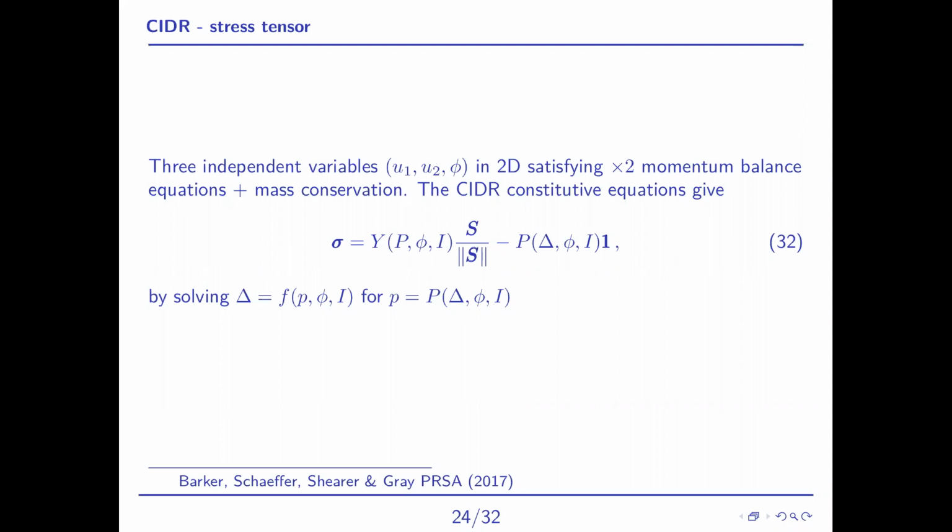And so you can process it like this, and you get an equation that looks very similar to the incompressible case for the full stress tensor, where now this y function plays the role of mu of I times p, and the pressure no longer responds to incompressibility and, say, gravity. It's a function then of the kinematic variables. The pressure is a response to shearing, a response to compression, a result of density of contacts.